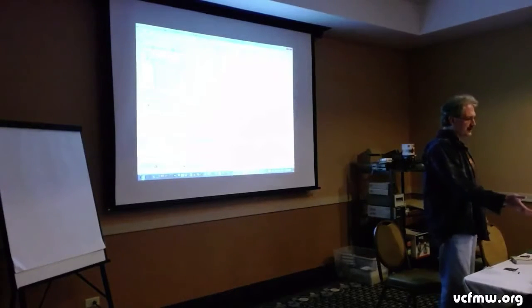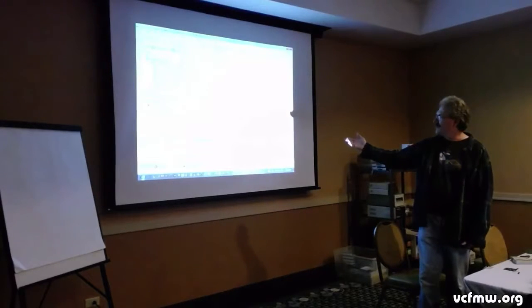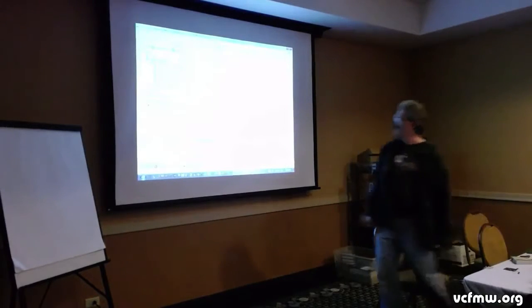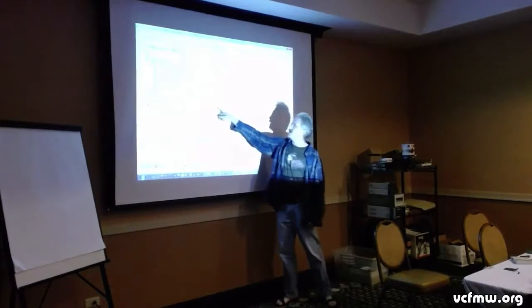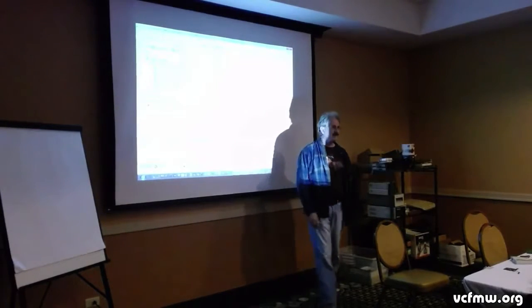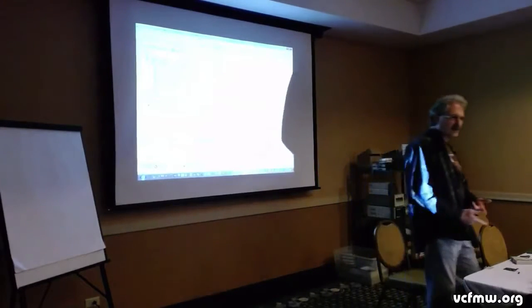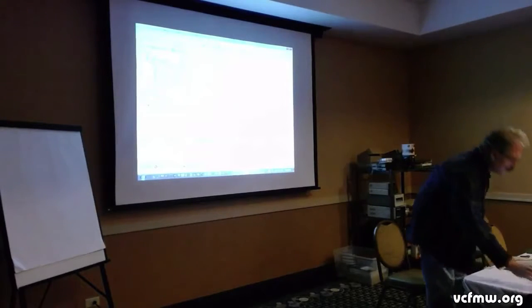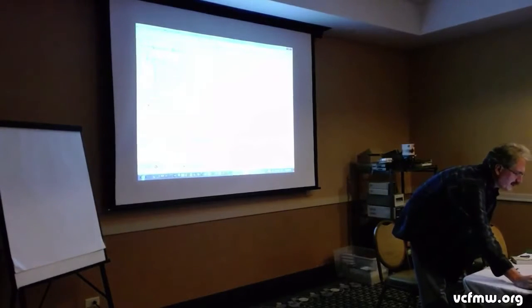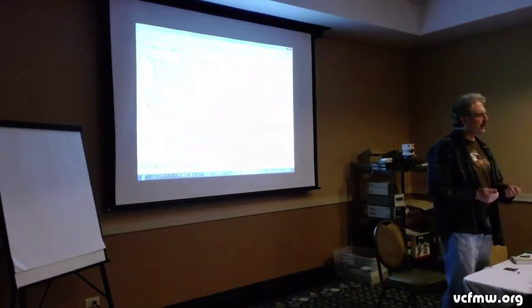But anyway, this is some of the stuff that you can see from Verilog. A lot of here you can do things like, some people who know C code should be able to recognize this. It's a ternary operator. So you say if the first value is true, then the first part of the statement is selected. If not, the second part of the statement is selected. One of the things that I wanted to point out here is most of this stuff is just assigns, which basically is just combinational logic, or combinatorial logic.